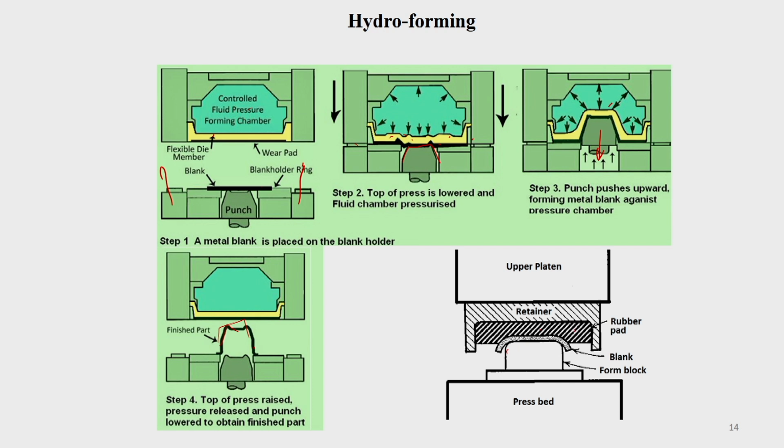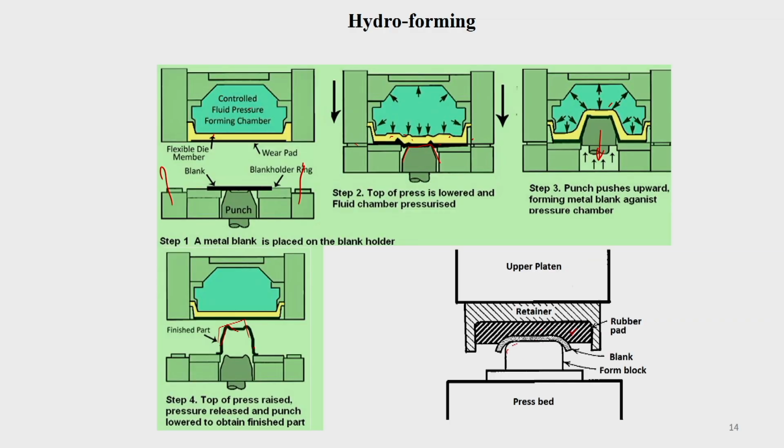Because of the rubber pad itself, it will give to some extent a hydrostatic stress, and due to that you can get the shape. So, on the form block, whatever the form shape is there, that you will get. So, that is what hydroforming is. Hydroforming is that way a very convenient thing. Only thing, initial investment may be high, but compared to the production rate, that will be balanced off.